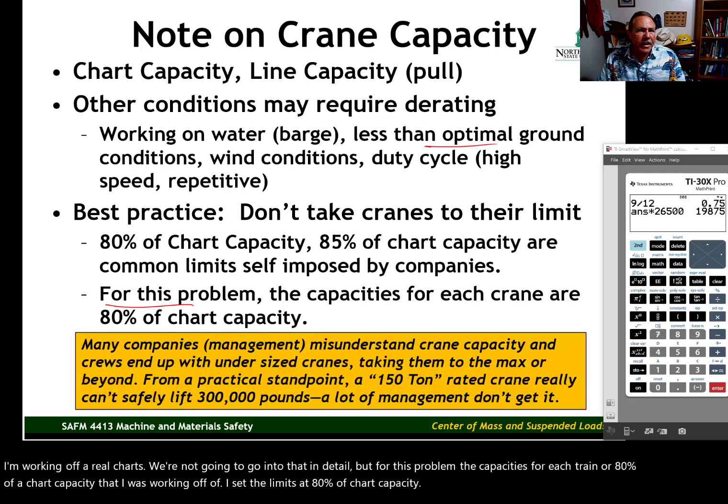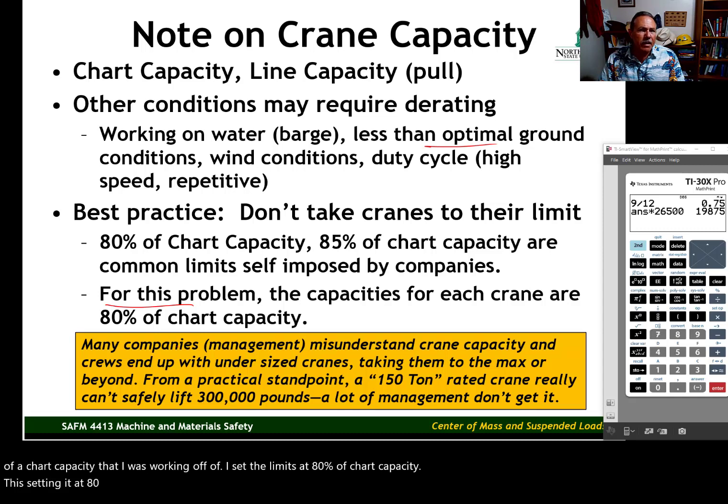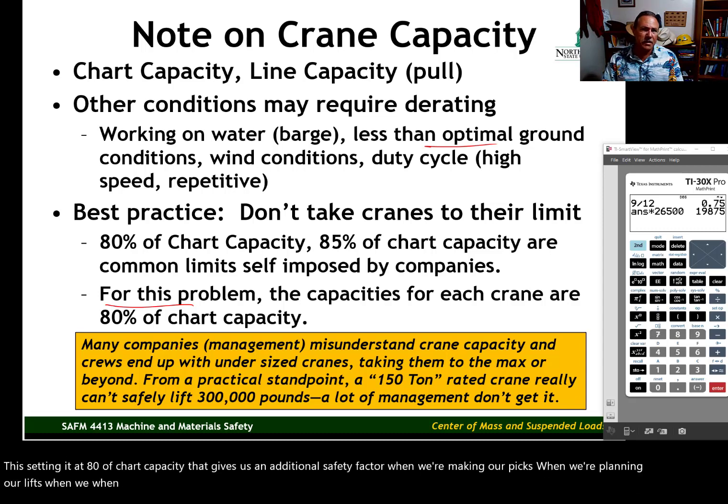Setting it at 80% of chart capacity gives us an additional safety factor when we're making our picks and planning our lifts. When we reduce our capacity, self-imposing that reduction on our operations just helps ensure a safer operation.